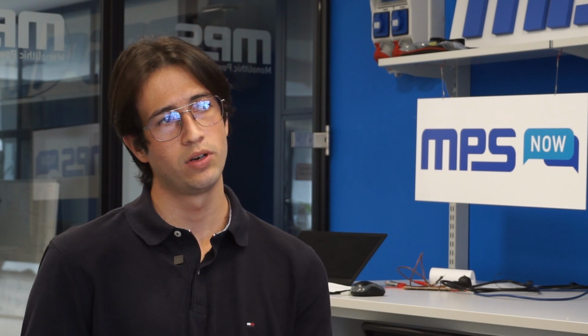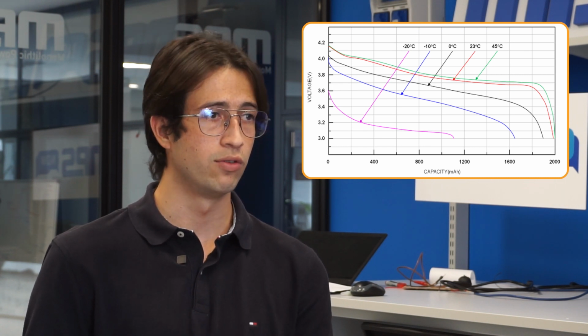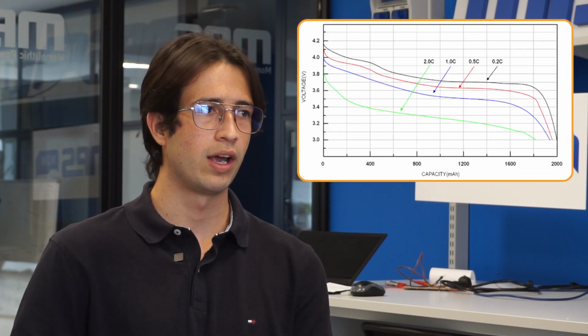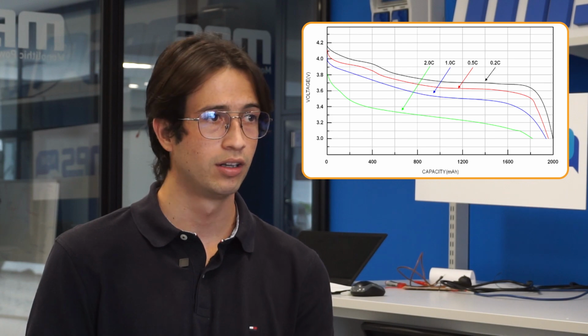We do a characterization with specific profile, current, temperature profiles. So we can extract the most important parameters of the cell. This means that we extract the open circuit voltage, we extract the equivalent series resistance, but we also extract the diffusion of the cell, so we can create a very accurate mathematical model of the cell, right?